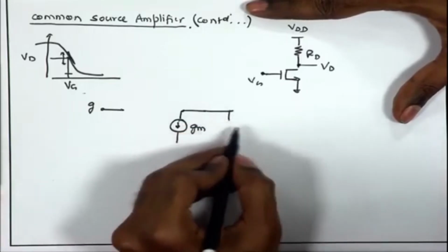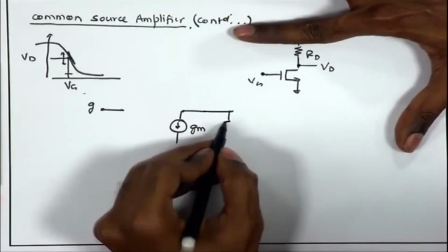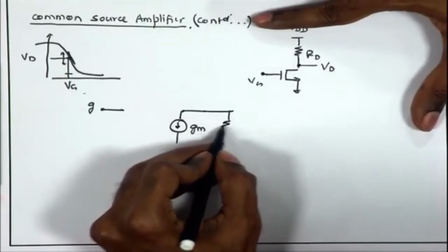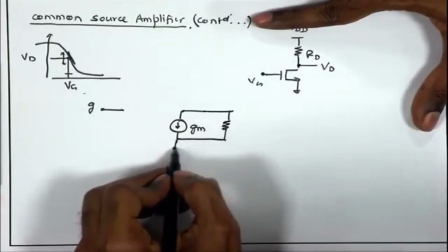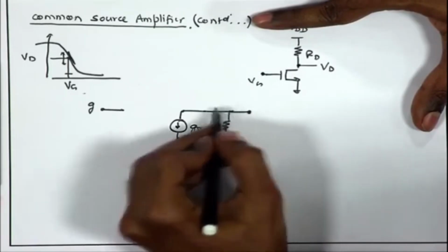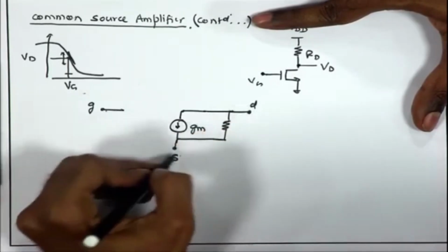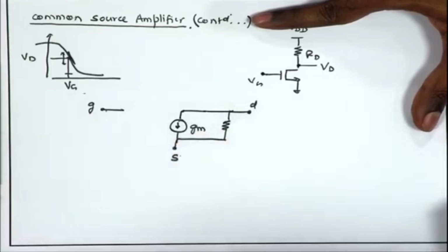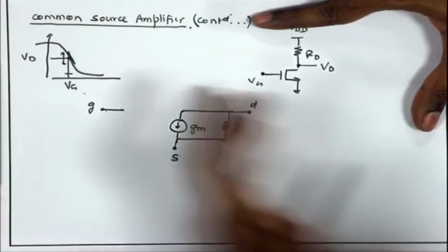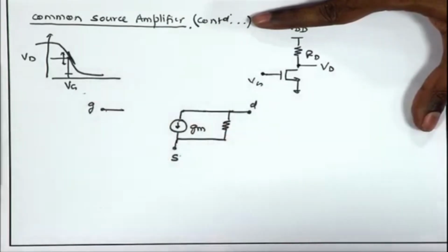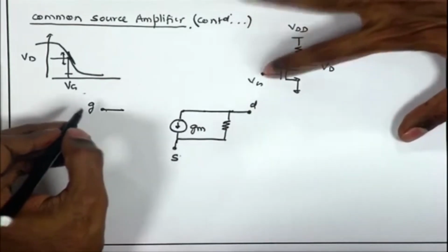So, assuming that the body terminal is grounded, we will be looking at how to include the parasitics also. This is the model of the MOSFET that we have at hand, 3 terminals, gate, source and drain, and now we have to look at the connectivity between these terminals and AC ground. So, first thing is what is appearing at the gate.